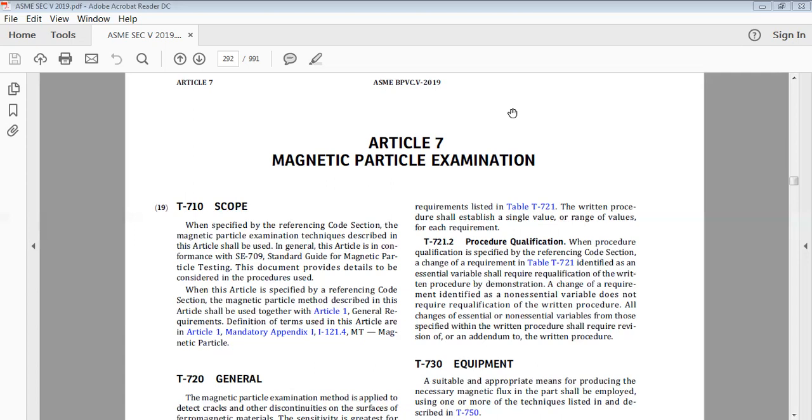It depends upon your job surface, because we use the powder which will make the surface contrast more. Based on that, we select the color of the particle. So sensitivity does not depend on the color of the particle, but the contrast depends on the color of the particles. Based on our job requirement, we change the color of the magnetic particles. Basically, red and black are the two common colors.